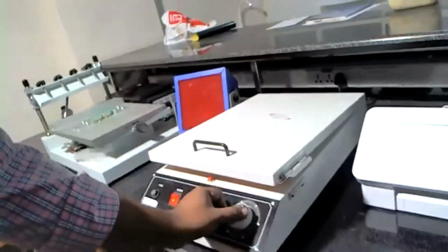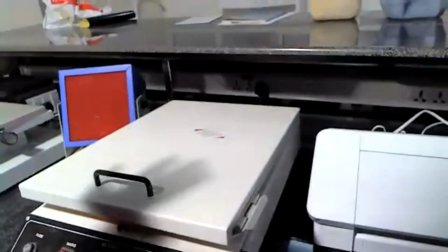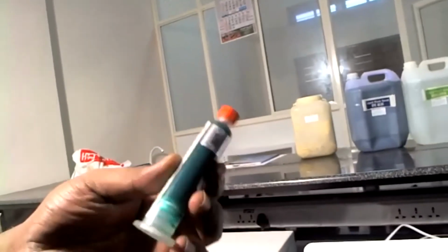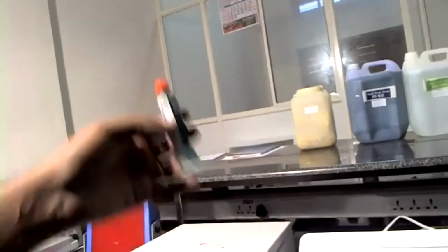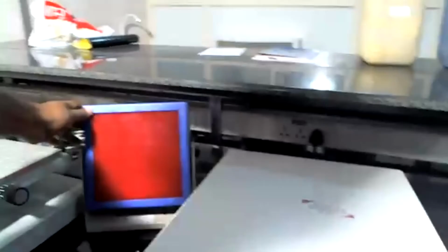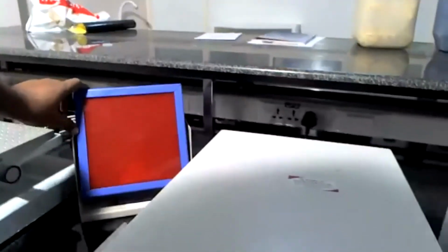Once it is done, what really happens? We have a stencil. The stencil will be kept on top of it. Sorry, they will apply this solder mask, and on top of it I'll keep the stencil. I'll let it dry for another 15 minutes. Then it will be developed. The trace areas will be removed and the other areas will be kept. More often we use this light while doing the development process because it will not etch off your board. It will safeguard it because it's a yellow lamp, so it will be safer.